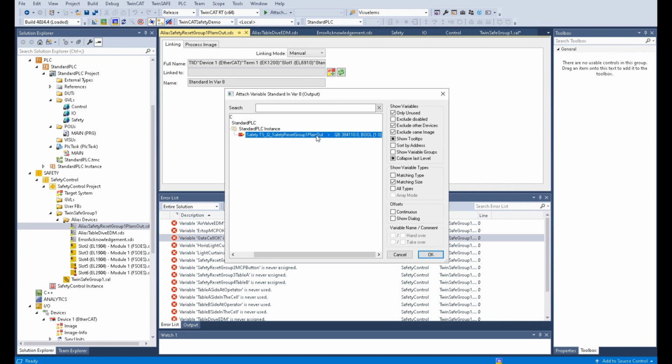So up to here, I need to mention, you can see basically for one signal, we have 3 areas. One is the standard PLC area, one is the alias name, and one is the tag in that mapping list. To align them together, I prefer to use the core name. If it is the same signal, the core name, you'd better use the same name.